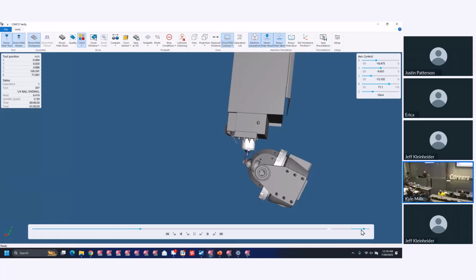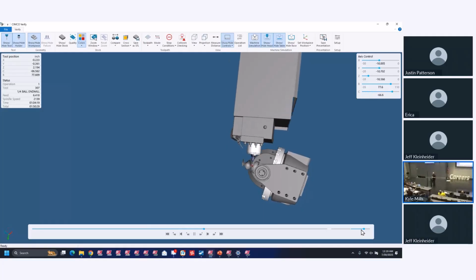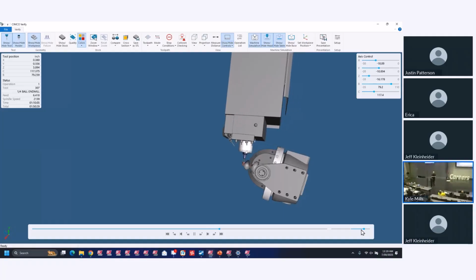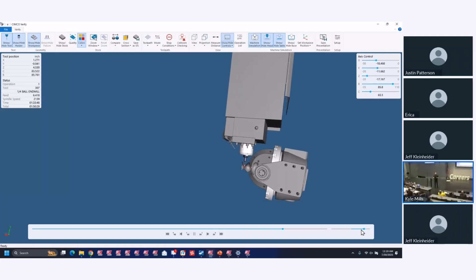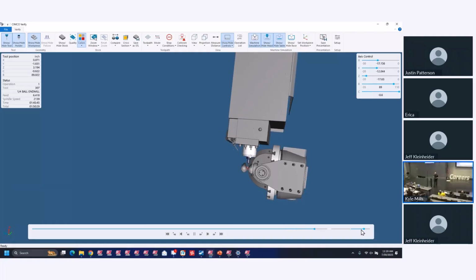And this is before we ever get to the powerful stuff that Justin showed us in collision. Think about those in tandem, what they could do. I might be hitting a few little red marks in here. Collision's going to take that right out. The thing I really like to impart is when you use collision to tilt to avoid, it puts a lot of motion in your machine. So I really like to take all of that motion out as much as I can and just use it very, very sparingly on that side.